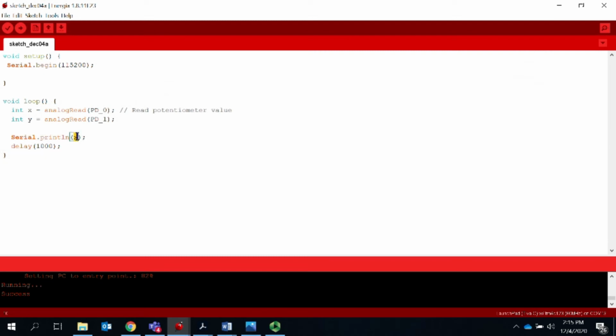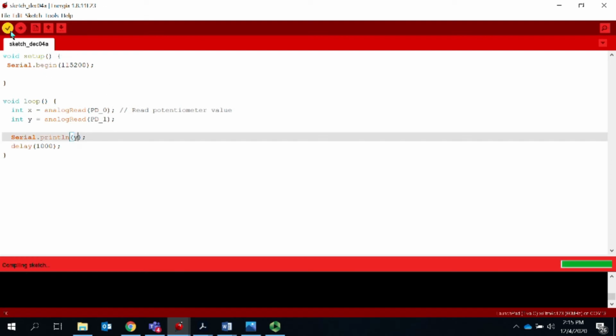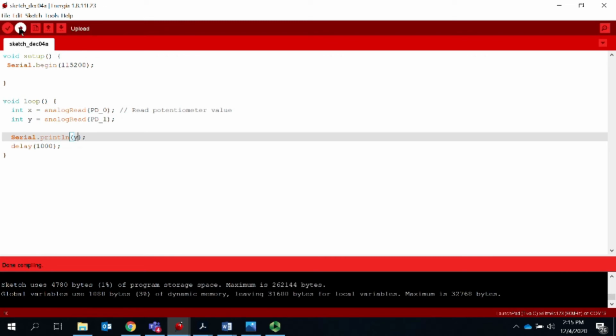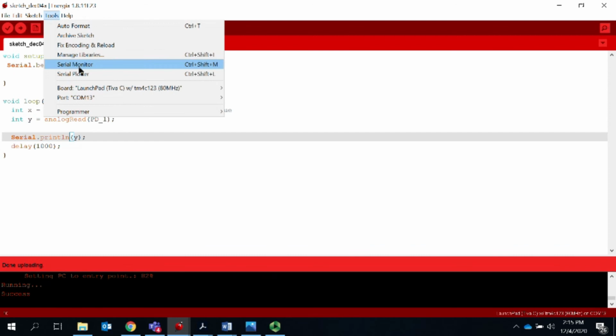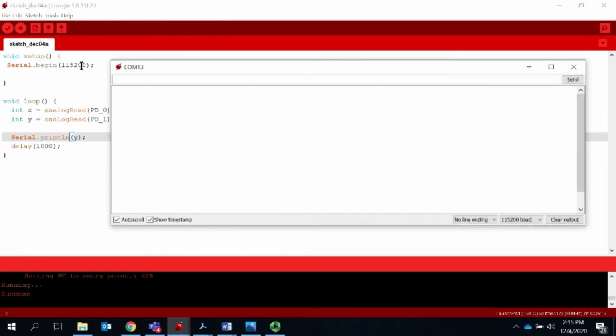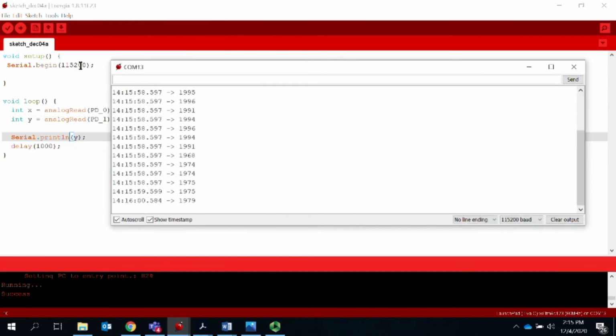So let's do the same thing for the y-axis. We go back to our code and change these to Y and see what we have on pin Y of the joystick. Let's load the code and take a look at the serial port. Now the joystick is in the center. Again, you get a number around 2048. Almost, with the tolerance, you see it is 1975, which is acceptable.